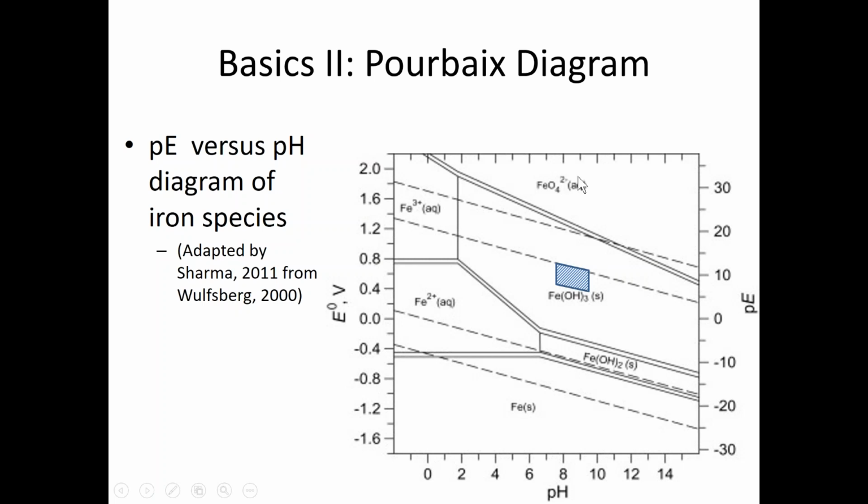And so when you add it to water, it wants to oxidize something so it becomes reduced. And it wants to go in this direction, heading down in this diagram. On the bottom, you see Fe(s) way over here, and that is the iron metal that we have in pipes. So it's a solid zero-valent iron that in turn wants to, in this case, go up toward the zone where water treatment normally operates.